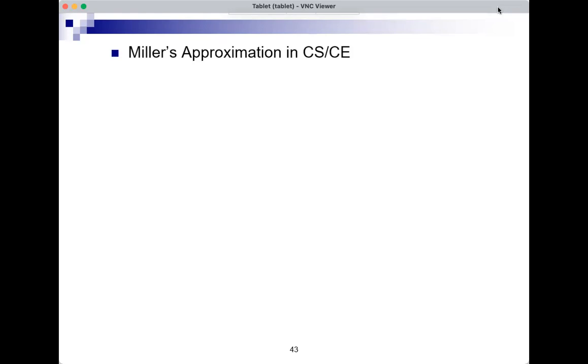So what's the approximation that we will use? We will use the low frequency mid-band value of VO over VGS, V2 over V1, that we get if there are no capacitors in the circuit. So we will find K at low frequency and then say that, okay, this is K and it's fixed, it doesn't vary, and use it and apply Miller's theorem.